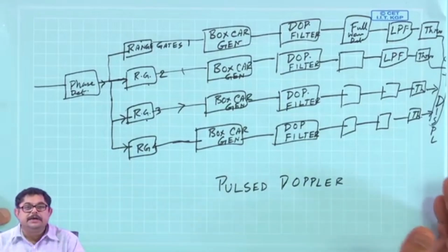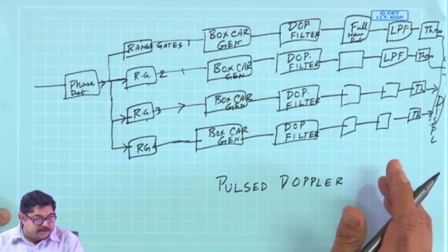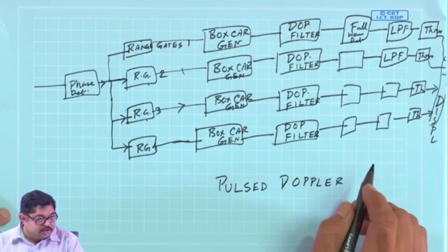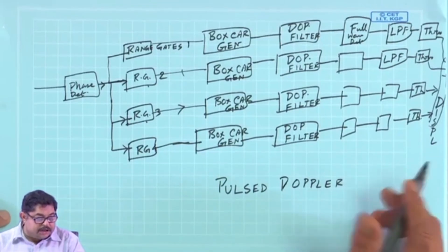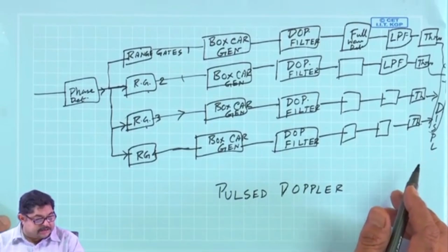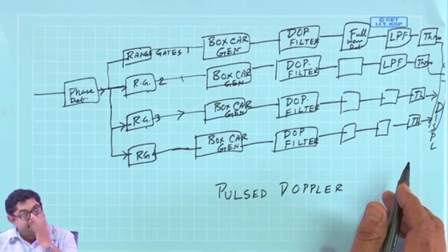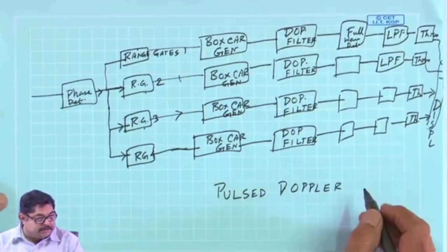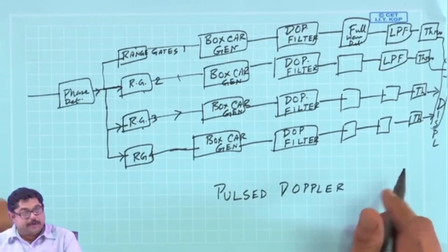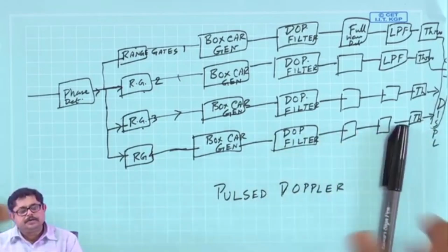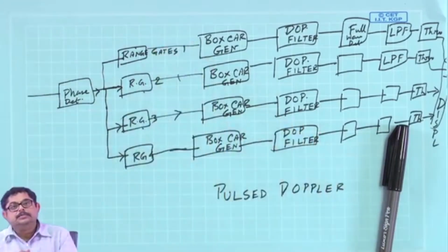The price paid is the cost of the Doppler filter. It is very narrowband, so that the Doppler resolution is good and there is good clutter rejection. Usually the MTI improvement factor of pulse Doppler radar is much greater than low PRF MTI. Also, many range ambiguous pulses are entering the Doppler filter, so more improvement factor is needed here. So, this is a good design.